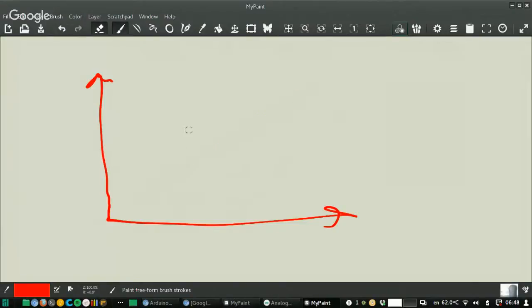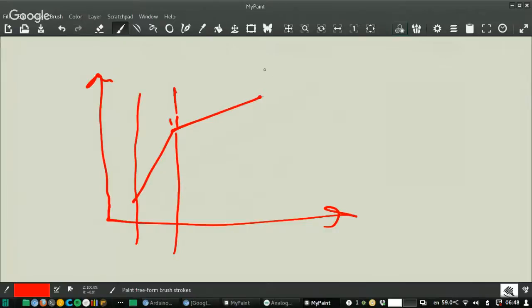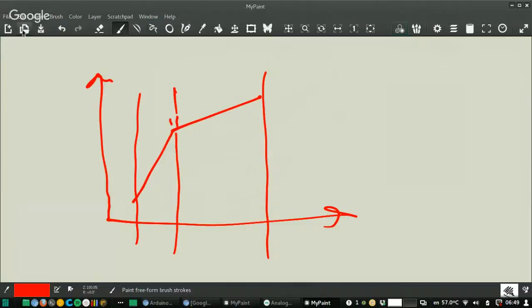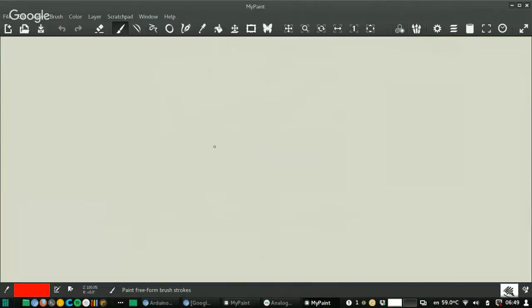So if it's linear like this, you have to divide the sensor in two and do one map here and one here, like two maps. You understand? You have to do two sections because the behavior is not linear. It's only linear in this chunk and in this chunk. And worse than that, is it clear? What's non-linear here? Exponential or parabolic or whatever kind of curve.